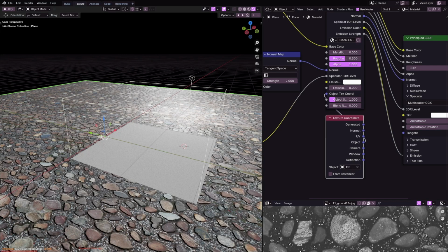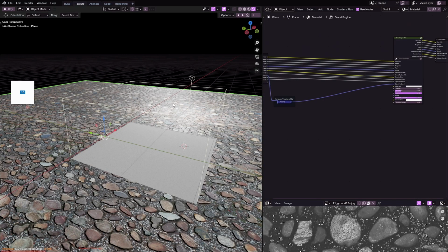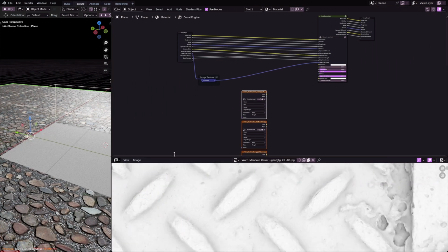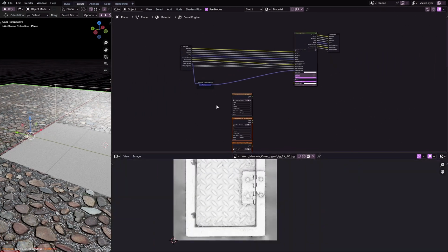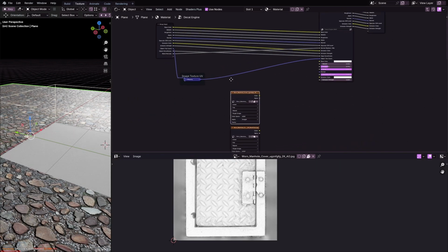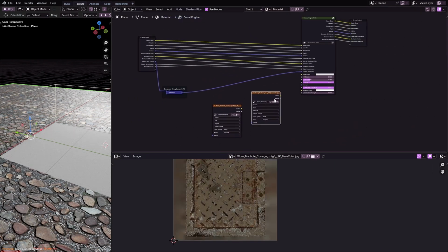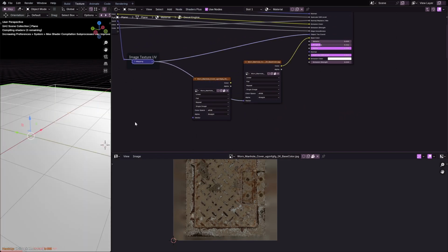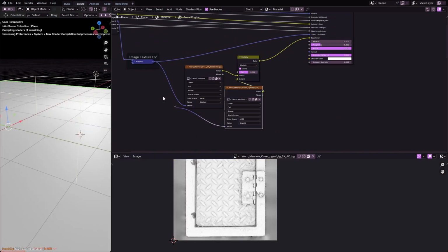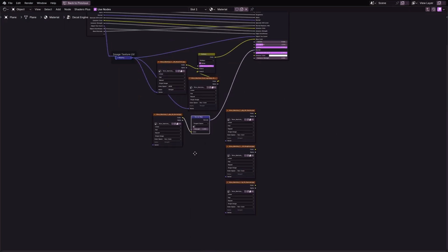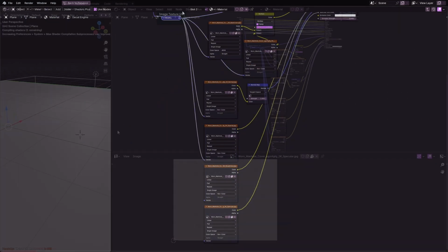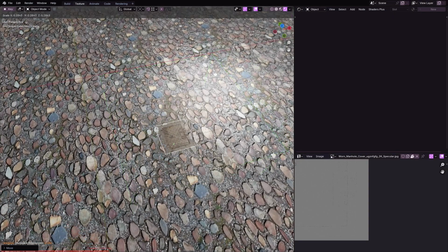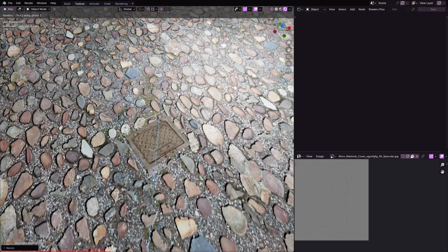Now to set up your decal, open the Decal Engine node. You see empty inputs similar to the Principled BSDF shader: a color, AO, normal. Link it all up as you normally would, being sure to link the UVs of any image texture to the image texture UV so their projection can be controlled. Now, with this setup, your decal appears in 3D space. You can move, scale, and rotate the cube to position the decal precisely.